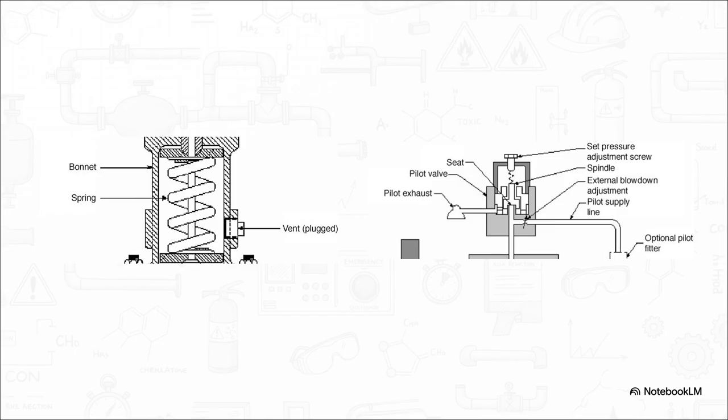It's beautifully simple. You have a massive, tightly coiled spring physically pushing a disc down to hold the pressure inside the tank. If the tank's pressure pushes up harder than the spring pushes down, boom, the valve opens. Pure brute force physics. But on the other side is a pilot-operated valve. This one's a bit more complex.